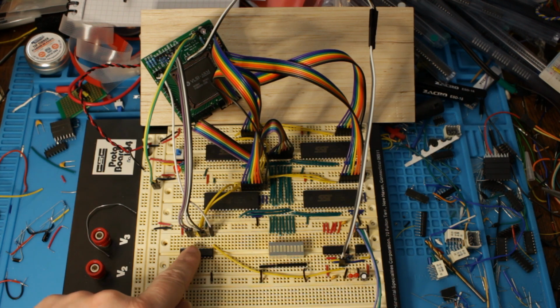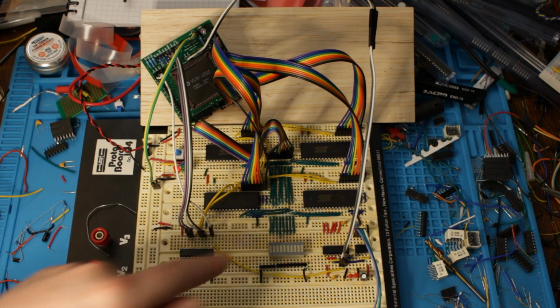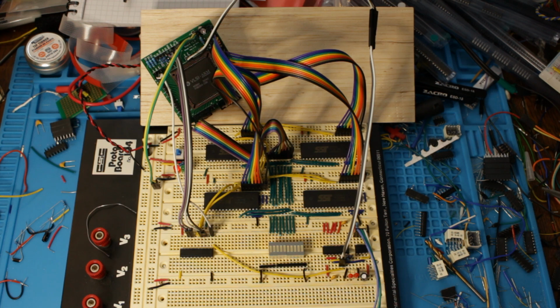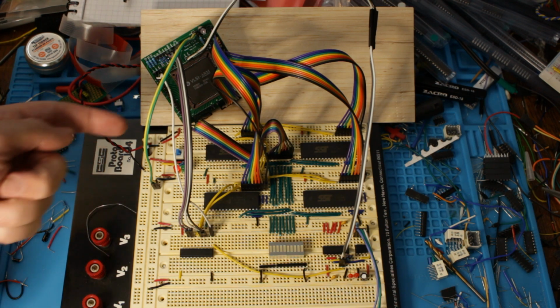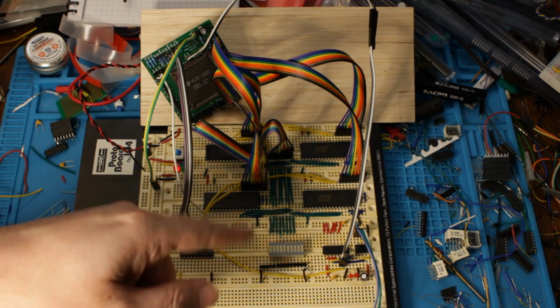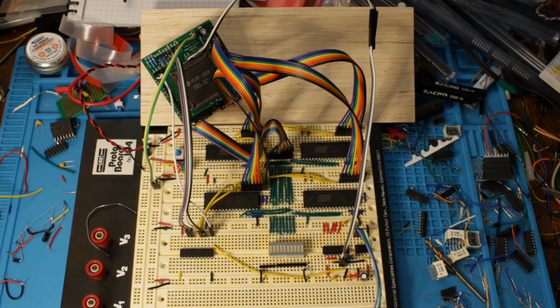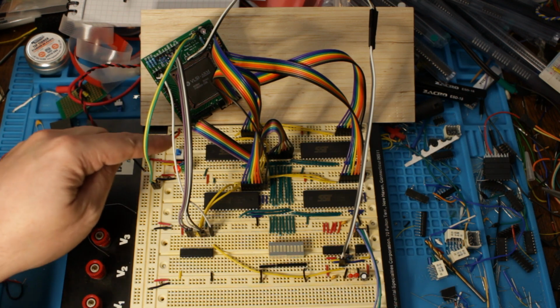And the outputs from the latch, as I showed before, are connected through to the control lines on the EEPROMs, or ROMs rather. These aren't actually EEPROMs, these are NAND flash or NOR flash or something like that, but they work the same way. Oh, and the address bus is also connected through down here onto the green wiring in the center of the board, as I discussed before. So let's see what happens when we turn it on.